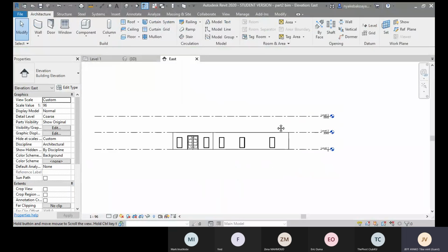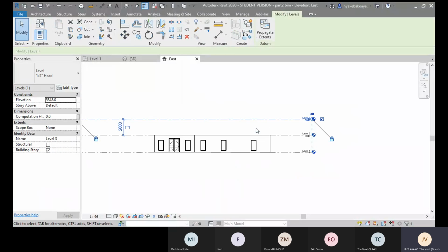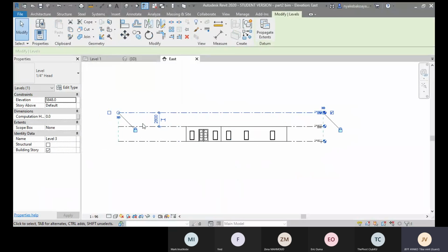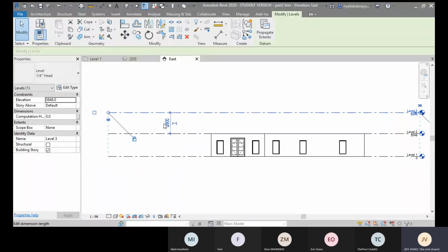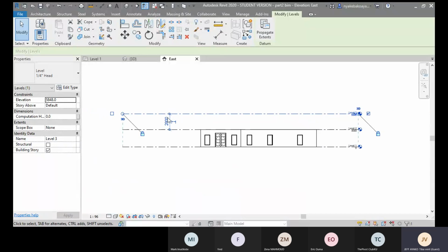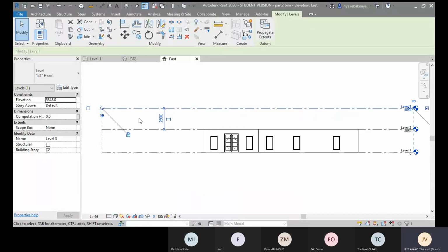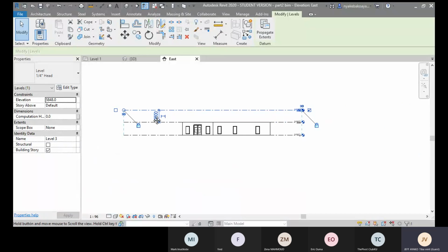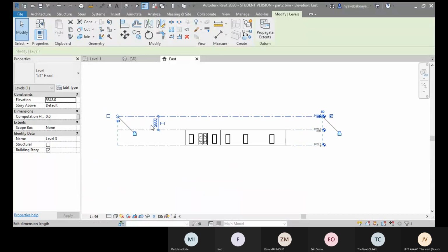We also need to, because we just did the placing, do the dimensioning. For example, when you click it, it gives you what we call temporary dimensions. And we have temporary dimensions, and we have the other ones, which we call permanent. So temporary dimensions come with these dotted lines. We call them witness lines.